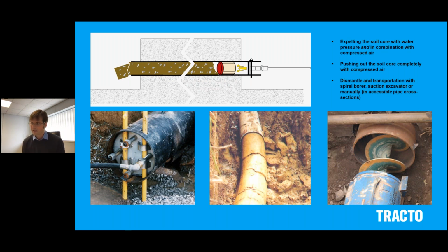In the rare occasions where it does, you would be able to pinpoint reasonably well where that happened, and you may even have to abort the pipe ram, because all of a sudden the spoil cannot be let into the product pipe anymore, and you might end up, in simplistic terms, converting your pipe ram into a soil displacement hammer, and all the soil will have to be displaced around the outside of the pipe, which may lead to heave that you are trying to avoid.